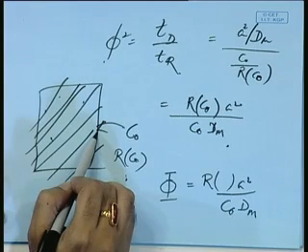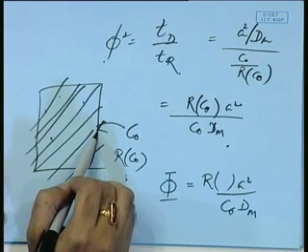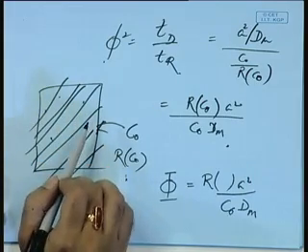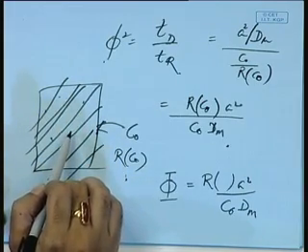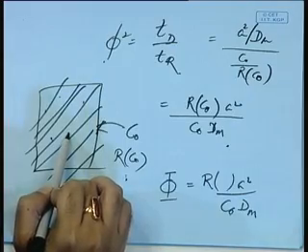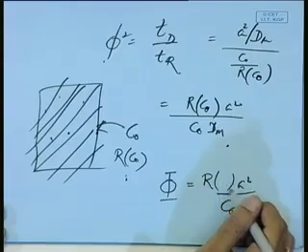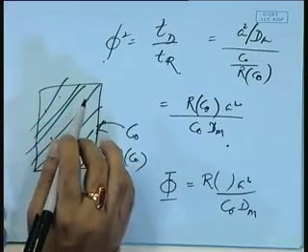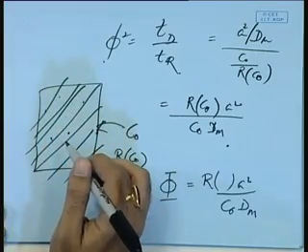See, let's understand two things, that the surface reaction rate is not a true representation. That's the maximum reaction rate possible because the concentration is maximum there, and concentration inside the matrix varies from point to point because of mass transfer limitations. Now, which point? This is a very straightforward answer. At which point should this concentration be measured? It varies from point to point. Do you agree with that or not? Then which point should we measure it?